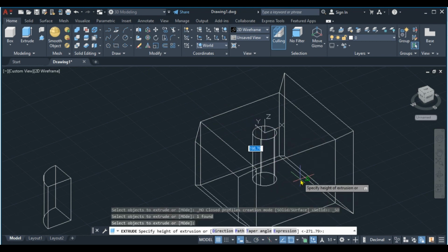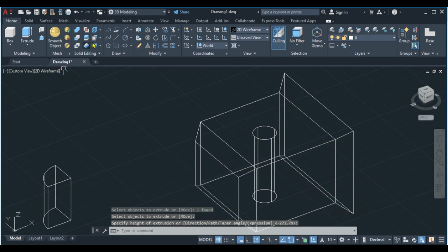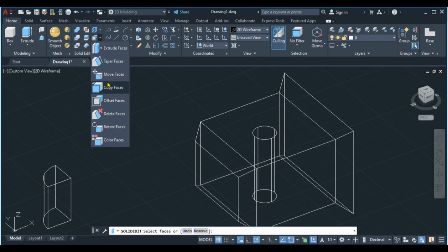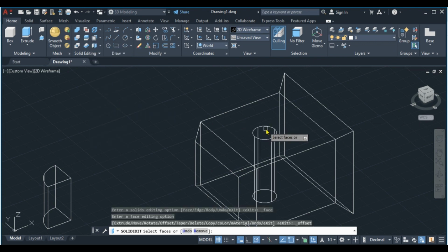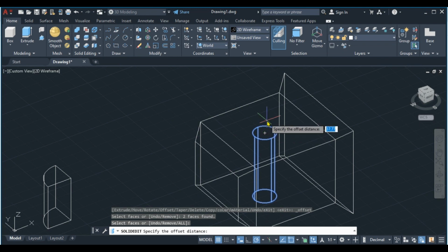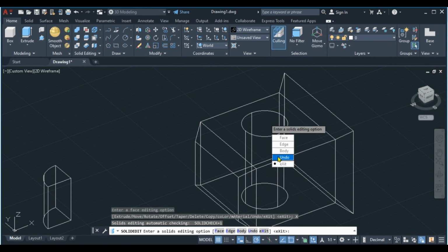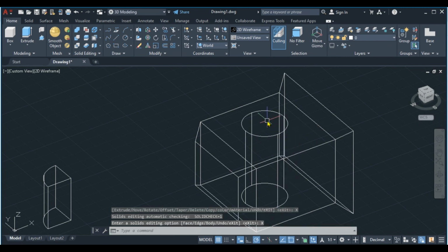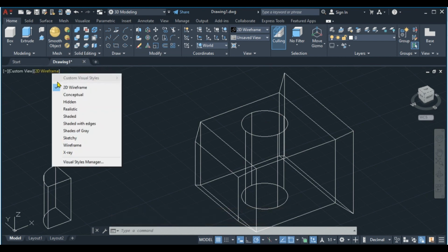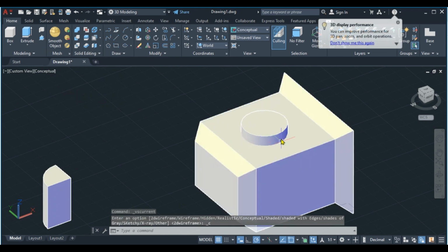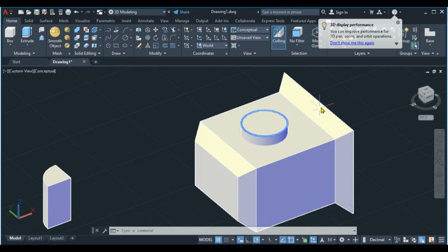Okay. Now I'll extrude to the base here. Alright, then do the offset. For instance, select this space first. I enter a value of, let's say, 40. Then I'm able to enlarge it. So the offset basically helps you, whatever shape, maybe the small, you can enlarge it, all of that. Okay, let's go to the 2D conceptual. See that right here, can subtract, can do whatever you want.